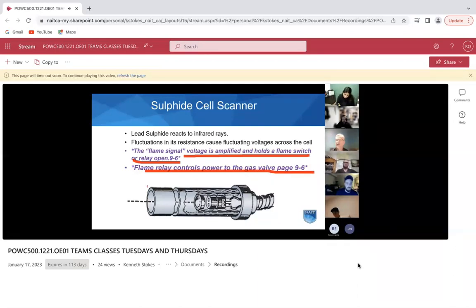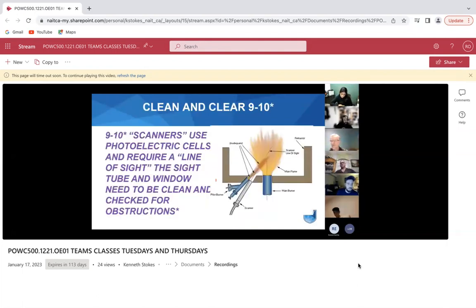So with this device, you don't want to have the flame in close proximity. The flame is over here, and the device is going to look at the flame and sense the radiation. So radiation will go to the device. If these get too hot, there are going to be problems because there are electronic circuits in them. So they're away from the flame. So here's our scanner back here.